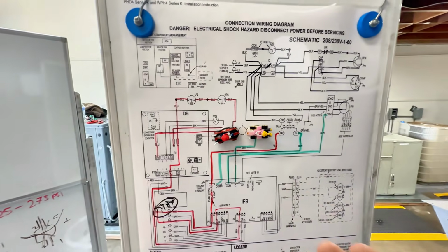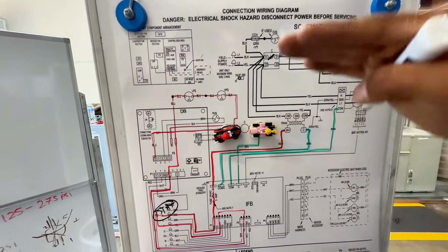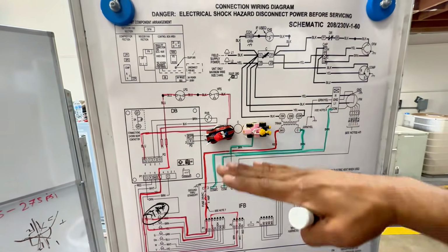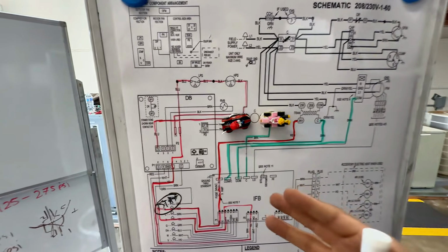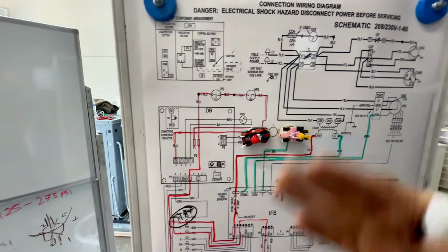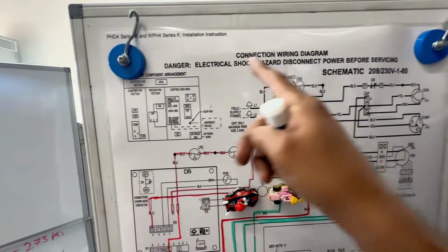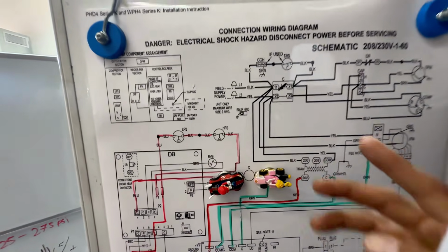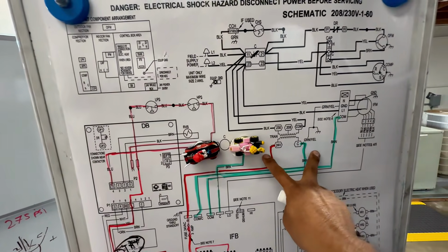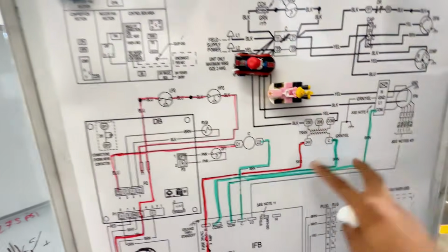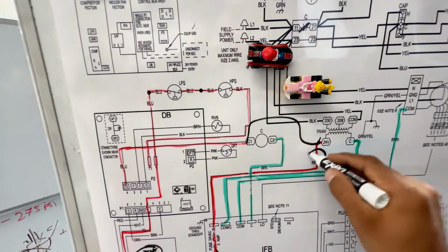But I just had to go with the ladder wiring diagram because that one will help you understand that all you're doing is using low voltage to control when you send 24 volts to the contactor coil to then send high voltage to go through and power up the components. And maybe in the future I'll do another video on the connection wiring diagram. But this is all there is to wiring diagrams. At the end of the day, can I take these two wires? Right? Can I take 24 volts and common and go straight right here? Just skip the whole thing and go right there. Right there.